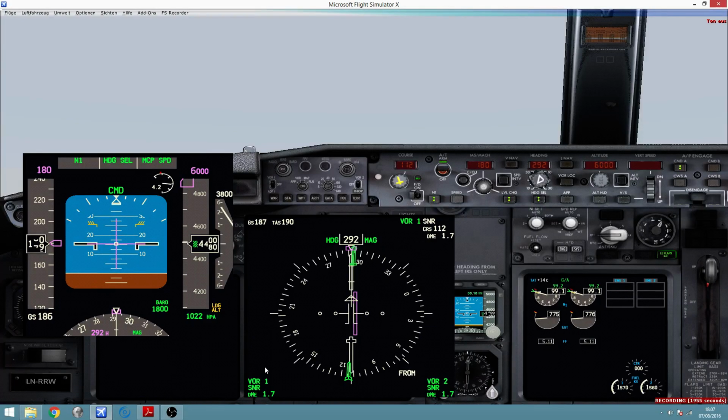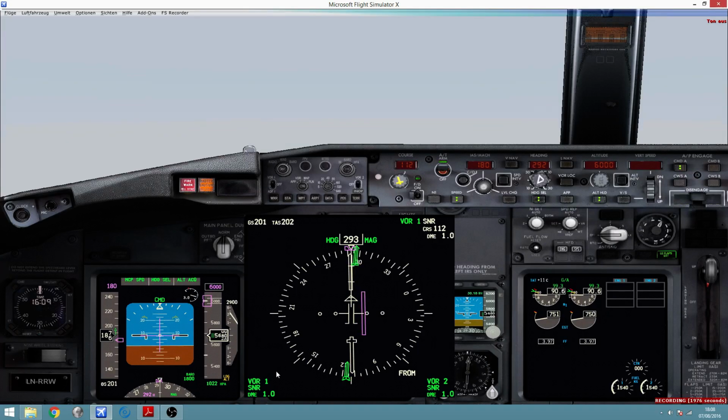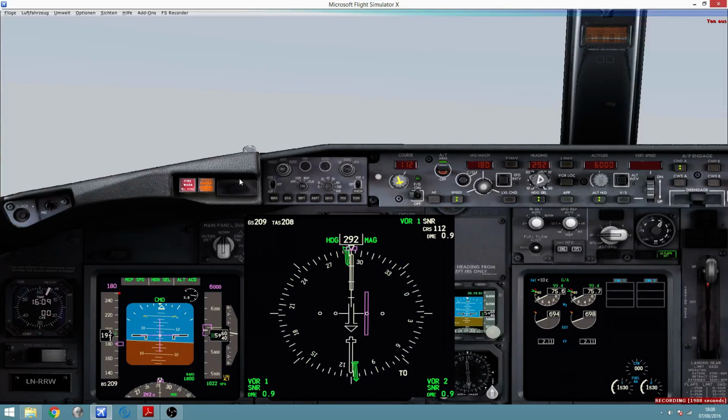So still approaching towards the VOR. I'm going to prepare the chronometer. I've just reset the chronometer. Okay, I'm about to reach 6,000. Since I'm going to maintain 6,000, I will continue flying with respect to QNH, because I will not penetrate the transition layer flying higher than that. Okay, I'm just now over the VOR. I start the chronometer. We'll continue on this heading for 1 minute. And then we'll turn right.